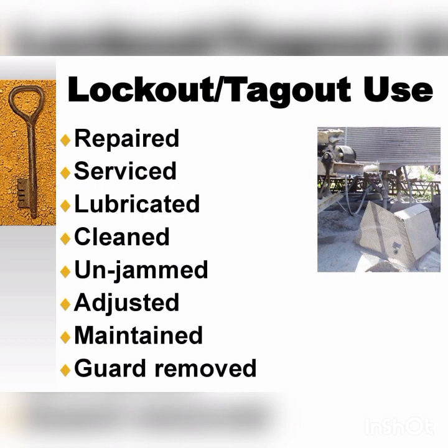Now we come towards the use and implementation of the lockout tagout system, where it is applied. When there is a repairing work, when you are going for a servicing job, when you have to lubricate the equipment, when you have to clean the equipment, when you have to unjam the jammed equipment, when you have to make some adjustment, when you have to do a maintenance job, when there is some guard removal from a system.